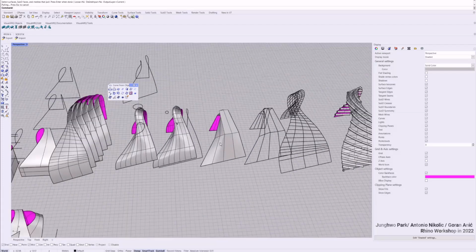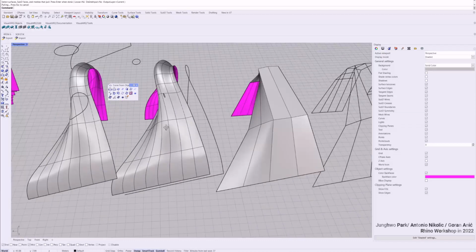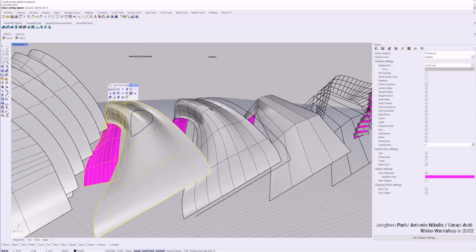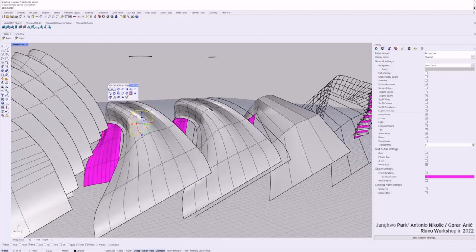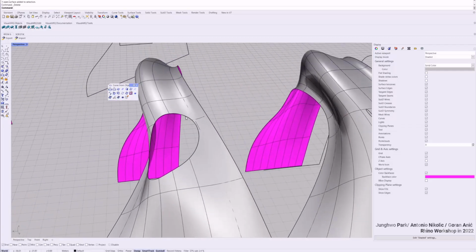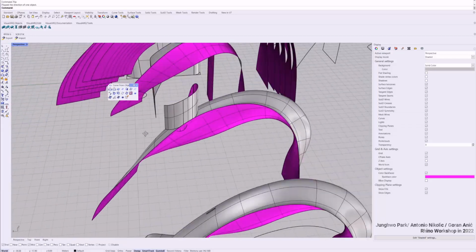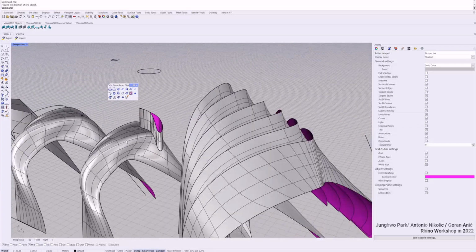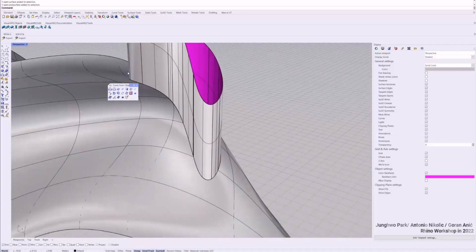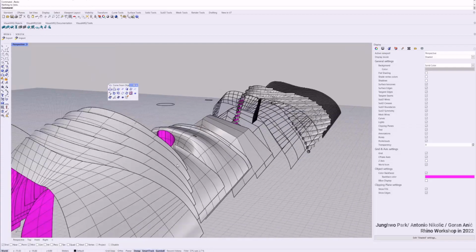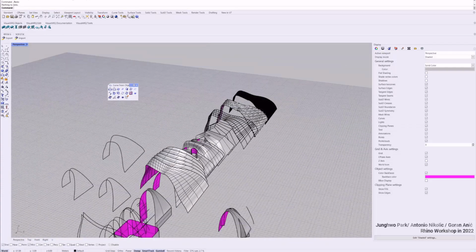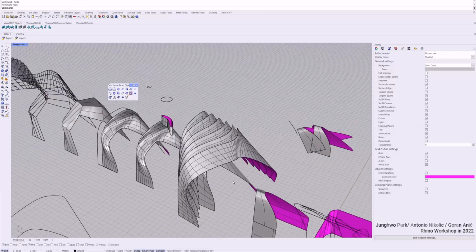Why do we use this? Because you can keep modifying your surface. For instance, once you project, you can split that curve, maybe take it out, and from that edge line maybe extrude it, whatever. You can keep modifying your geometry. We have here, for instance, fillet surface, so we can give the fillet vector between them and fillet it, but for that relationship we may look in more detail in solid geometry, because the solid fillet works better.